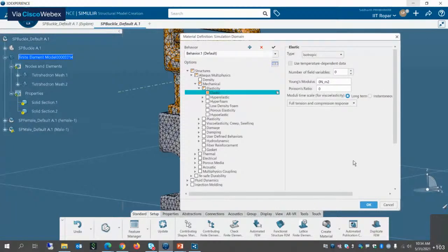And you can just expand it a little bit here, and we can give in the Young's modulus values. Okay, so the units will automatically be added if you delete them by any chance. So 2e+09. This is basically 2 into 10 power 9, the value which we are assigning for the Young's modulus. So E can be used there. And once you have defined the Young's modulus, the Poisson's ratio will be 0.394.